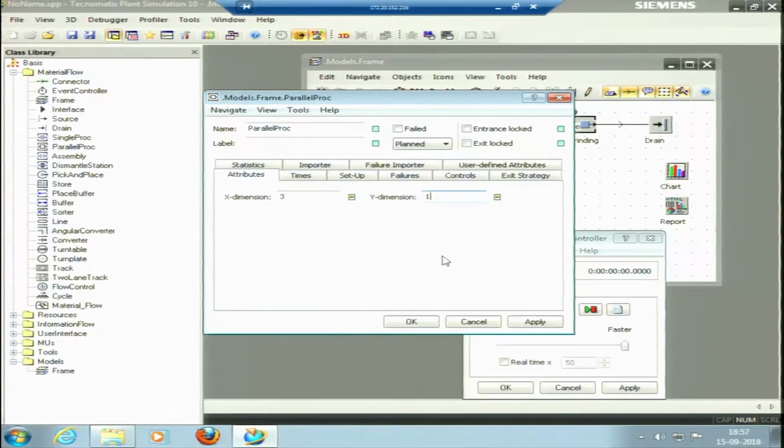For instance, there is one process that is being blocked for a maximum amount of time, for 40% of the time. It is being blocked for 40% of the time, that means the next process is taking more time for its processing, or it is taking an extended time. So this machine has to wait. So what we can do, considering other aspects, management aspects, is put in another machine, or we can double the capacity of the successive machine.